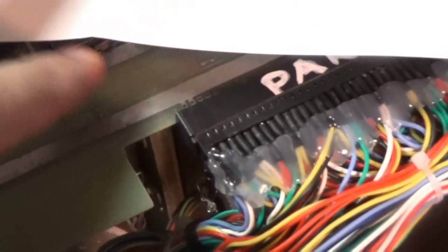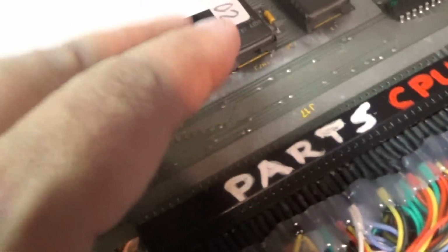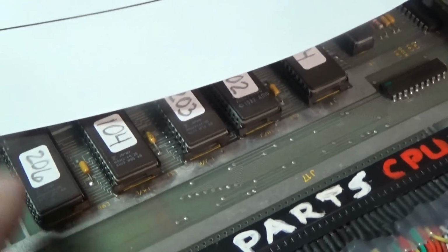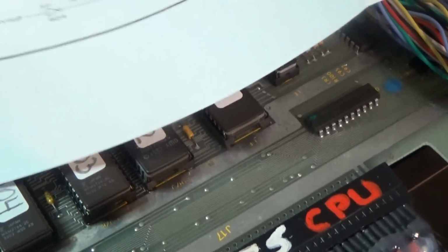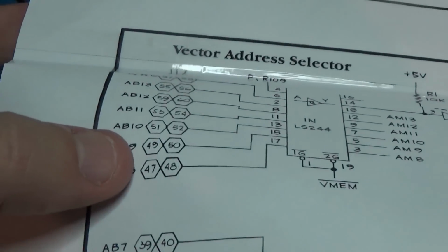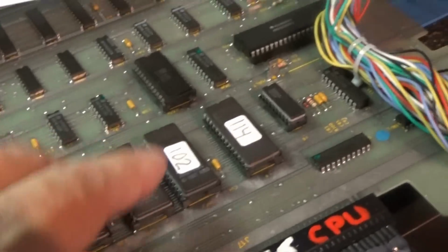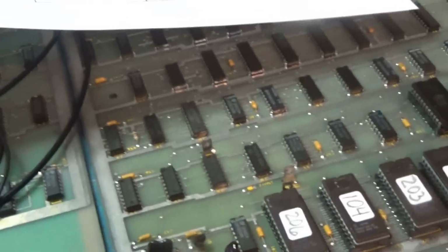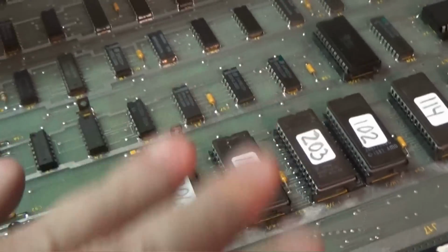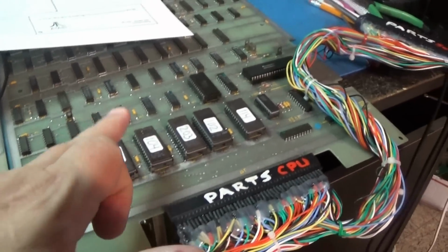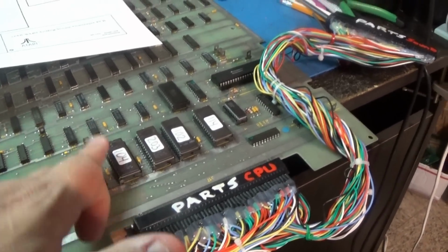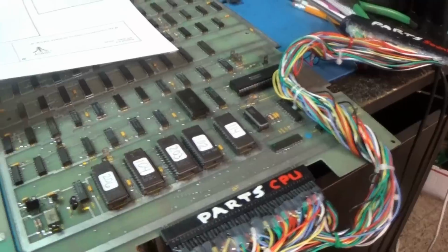So what I need to do is find address bit 10 over here. So let's do that. I'm going to look at the addressing, because that's direct AB. That's AB10. It's straight driven from this board through the connection over to here. I mean, it could be a bad connection, I don't think so, but we'll find out. I'm going to find address bit 10 over here, driven off of the buffer, and we'll see what's up.